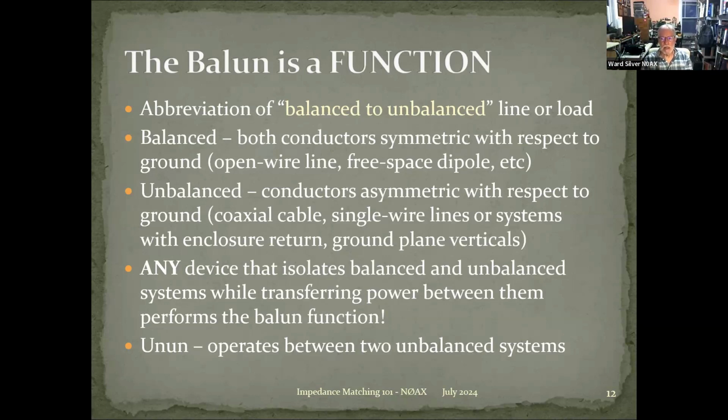So the function here is to isolate the balanced and unbalanced systems while transferring power between them. Anything that you do that performs that function is a balun. It doesn't have to be a coil, a transformer, whatever. There's a zillion different ways to do this. There are a lot of different types of balun. But that's a function. It's not necessarily a device. It can be a device that performs the balun function, but that's as far as you can go.